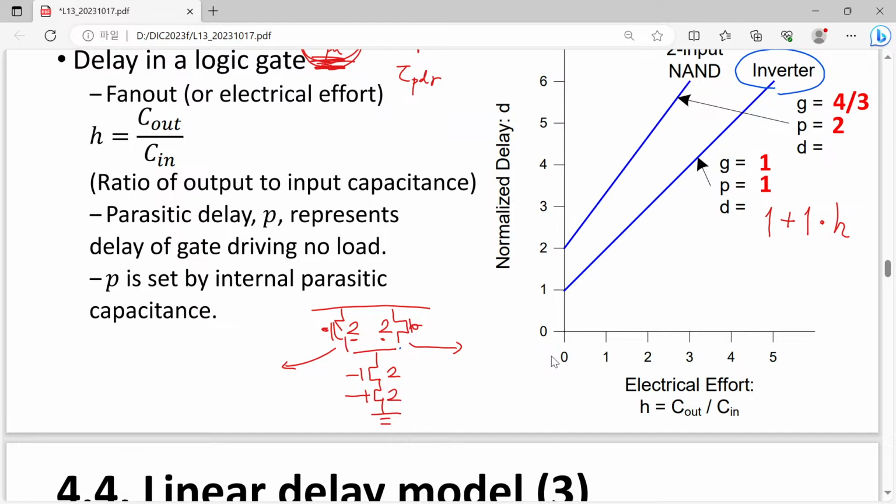So his question, in my understanding, is: when we consider the sizing of the pull up network and pull down network, how about considering the continuity of current flowing through this pull up network and this pull down network? So that is how I understand his question. However, first of all, we have to understand this type of CMOS transistor never allows direct current conduction between